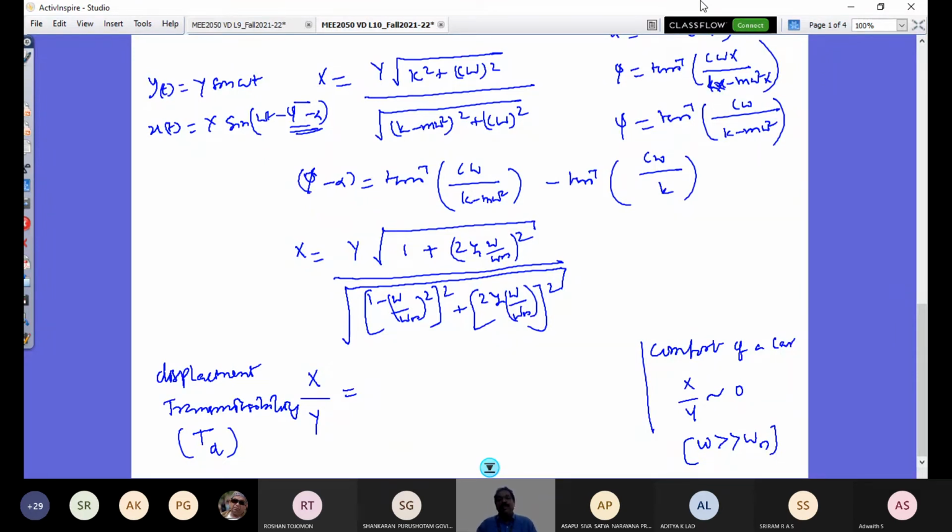Any vehicle would be tested for its endurance and durability. That vehicle, nothing would happen to the parts. So you would severely run it on a sinusoidal road, and you see what is the amplitude. So that amplitude, when you go very slowly, see your vehicle speed is not the excitation. Your vehicle speed, the road texture is what is your excitation here.